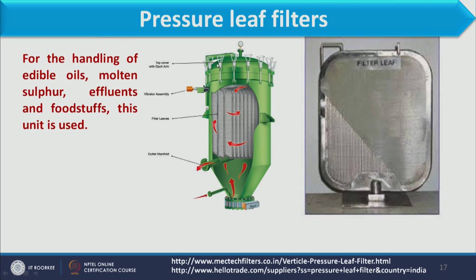As cake is deposited at the outer mesh only, the outer surface of the leaf only, filtrate penetrates through this and is collected through this pipe. All these leaves are connected with this pipe, where the filtrate which is falling inside the leaf is collected.